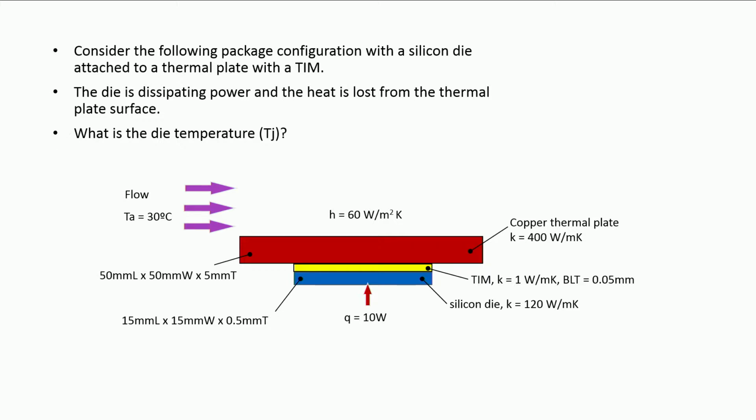So, you will put a grease over there and try to fill in those voids, so that now you do not have an air gap; you have those gaps filled in with something which has slightly higher thermal conductivity, 1 watt per meter Kelvin. Not great, it is pretty low, but compare that to air, 0.026, and it is wonderful, right? I just increased it by 50 times. All right.